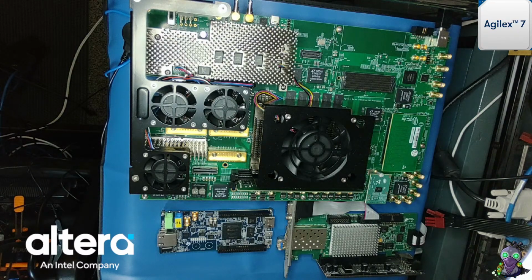Okay, so first we're going to go ahead and add the pins. This shouldn't take but a moment. Then we're going to look at the Signal Tap and get the D in and D out going. So this is going to be AE52. We're going to say the IO standard for this is true differential.